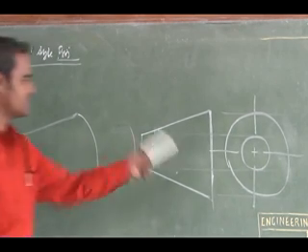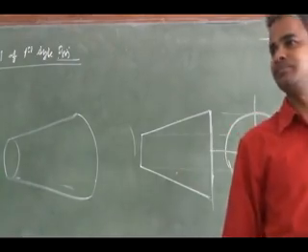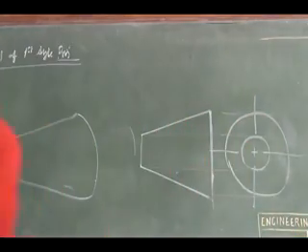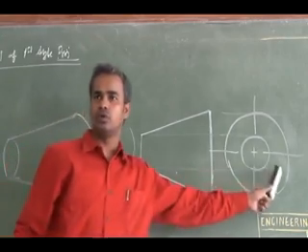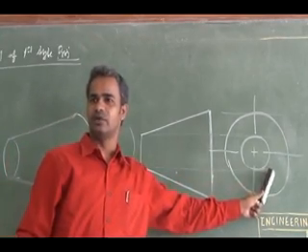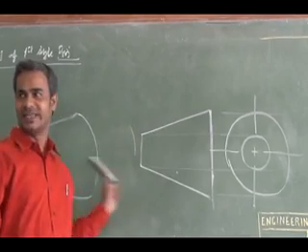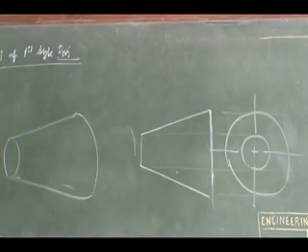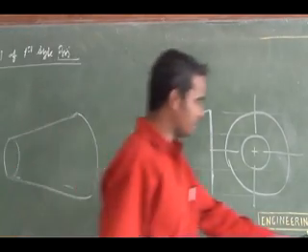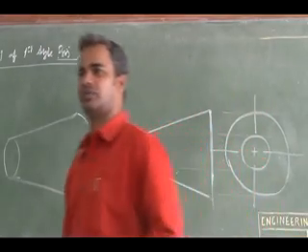Yeah, these two circles will come to the left side. The same left side view, what I am viewing, I will be drawing to the left side itself. The same left side view will come to the left side itself as for third angle projection.